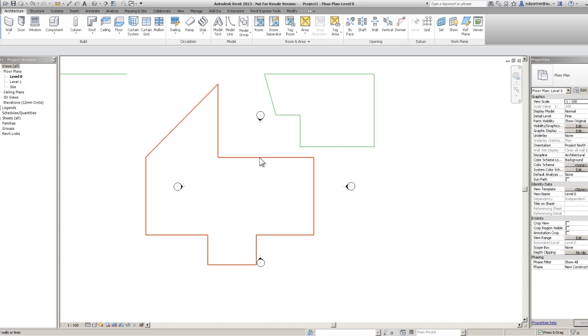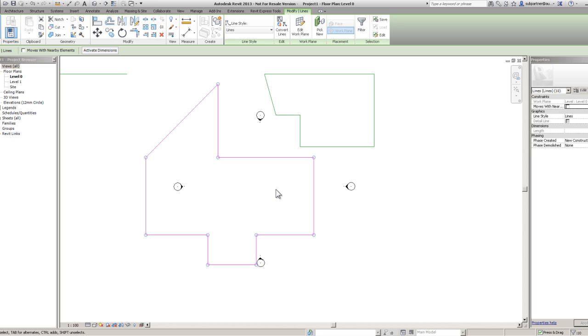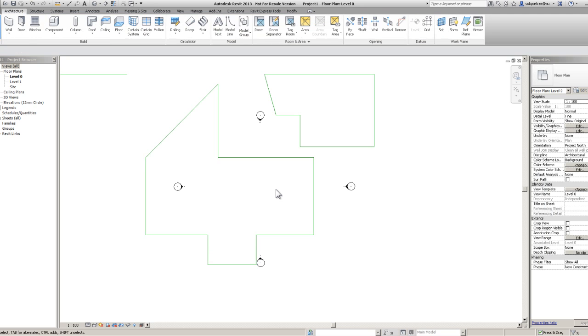If I just left click now, it's going to select all the lines or elements within that chain. I'm just going to unselect them by clicking in a space. Now, a little mistake people make: they quite often hover over it, hit tab, then move their mouse. Because it's only a soft select, a temporary selection, if you move your mouse off it, it's going to drop that. So just have a little practice of it.